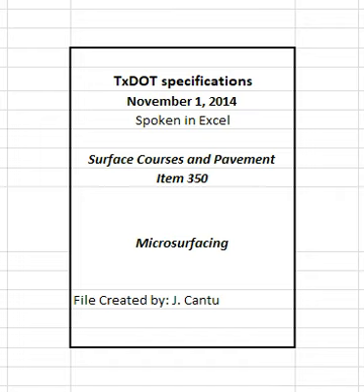The engineer will immediately report to the contractor any test results that fail to meet the specification requirements. Note that mix placed after test results are available to the contractor may be considered unauthorized work if the results require suspension of operations. Unauthorized work will be accepted or rejected at the discretion of the engineer in accordance with Article 5.3, Conformity with Plans, Specifications, and Special Provisions.